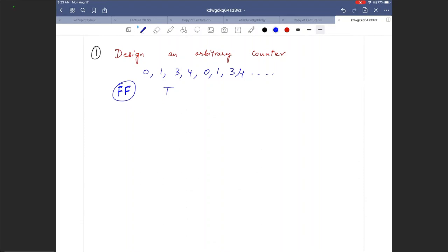D will give you an easy next state table, and the excitation tables are easy. However, after that, the step is for Kmaps and then drawing the logic functions. That might be complex. So just keep that in mind. T for counters in general is easier, right? So I would prefer T, but all right, it's good to know that you guys like D as well.